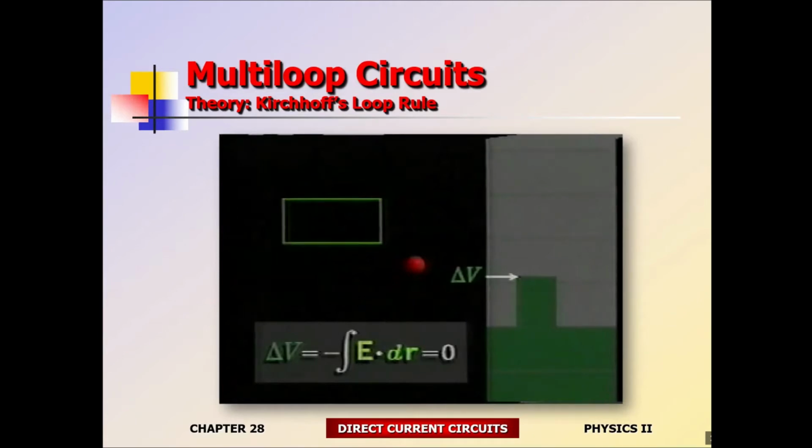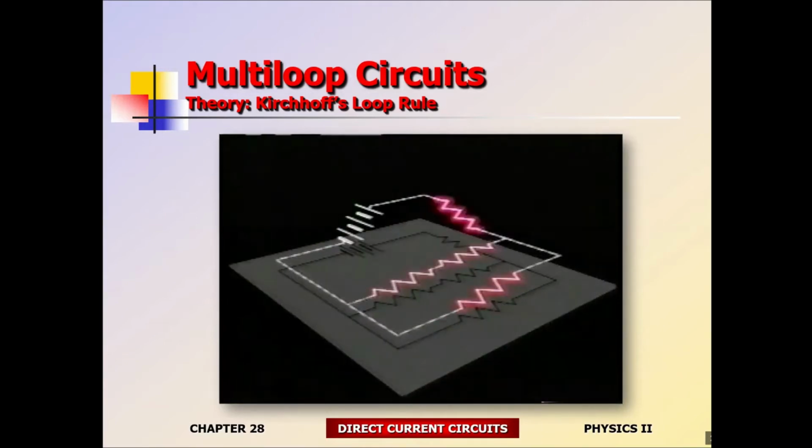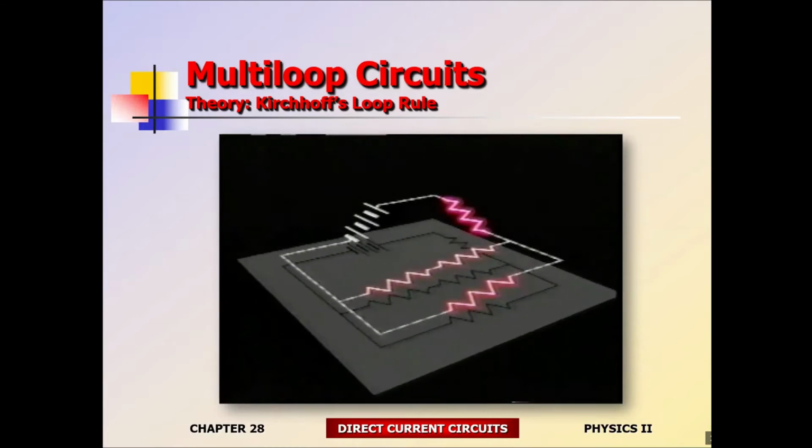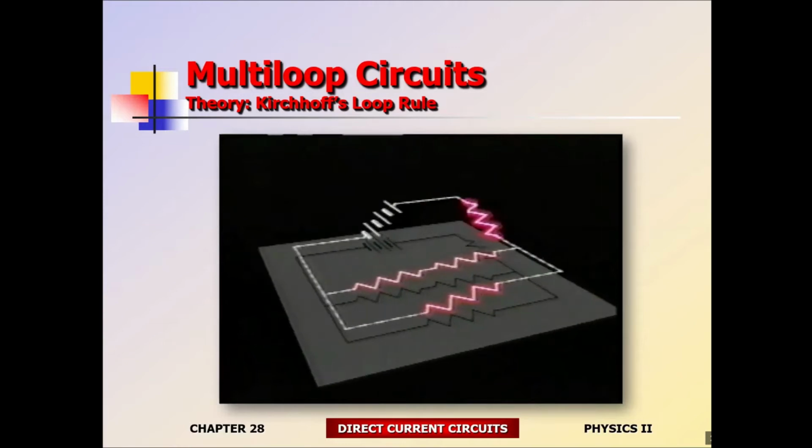Notice that an integral along a closed path has a special notation, an integral sign with a circle on it. So, in the special case of an electric circuit, all the voltage rises due to batteries and charged capacitors, and all the voltage drops due to currents flowing through resistors add up to zero. Using these two laws alone, engineers analyze the most complex circuits.